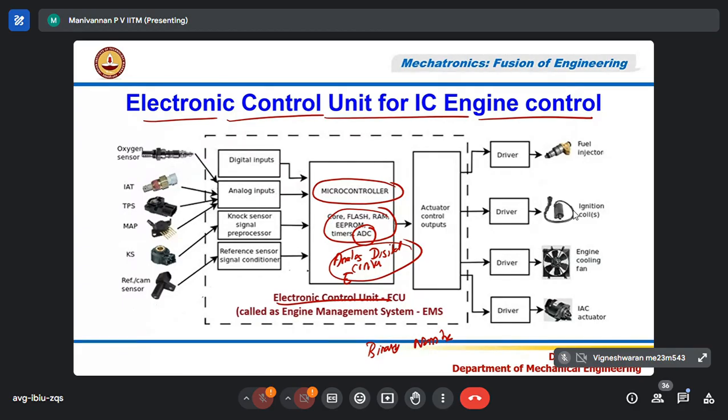I am going to talk about what ADC is and how it works. Right now, you understand that the signal coming from a sensor is an analog signal. Analog signal means the x-axis we always represent in terms of time. Time is 0 seconds and goes to infinity. The y-axis is nothing but signal strength, which is always measured in terms of millivolts or microvolts many times. Most of the sensors, if I say the pressure sensor, if pressure is varying from 0 to 10 bar, the pressure sensor will give a signal like this. So this is the signal coming from the pressure sensor. It is varying in millivolts.